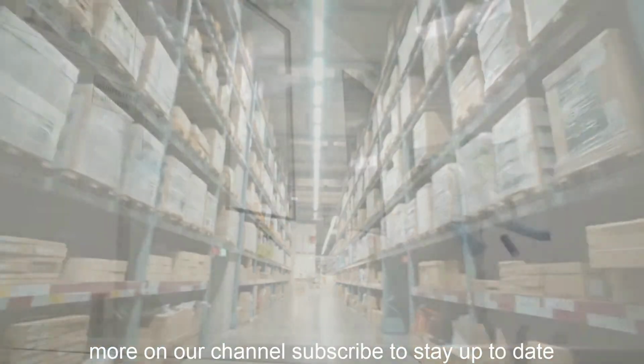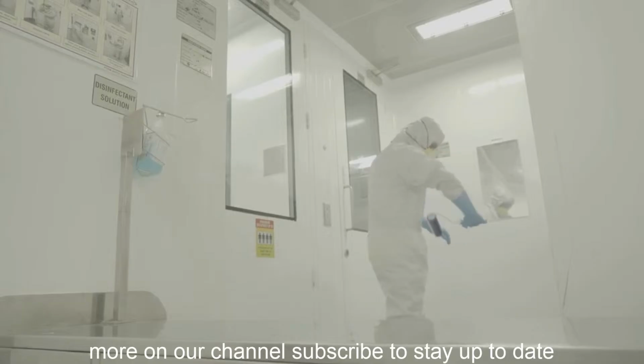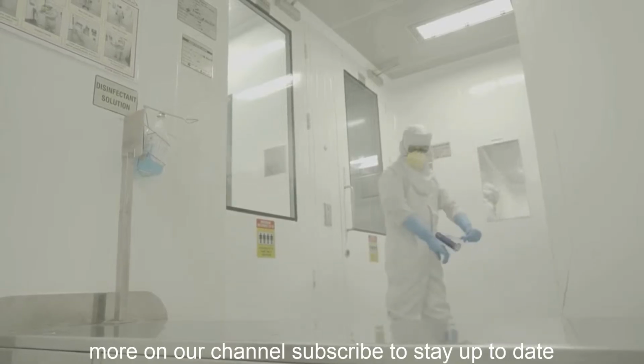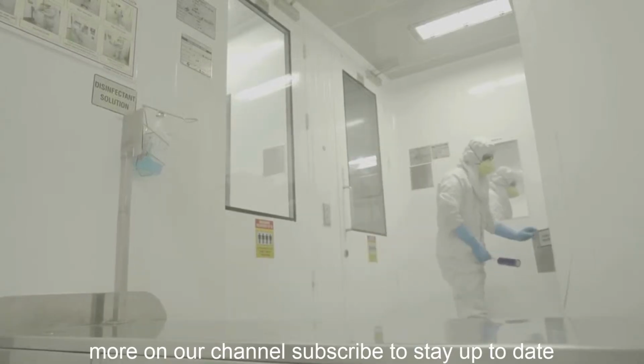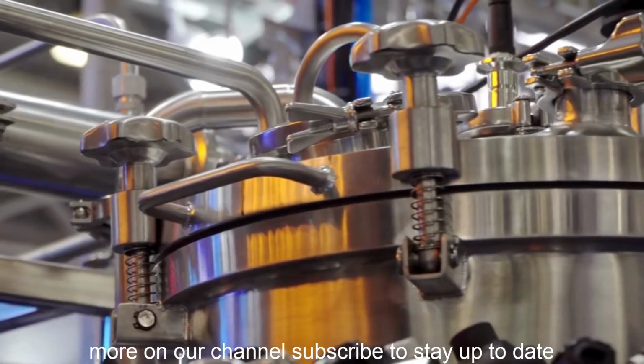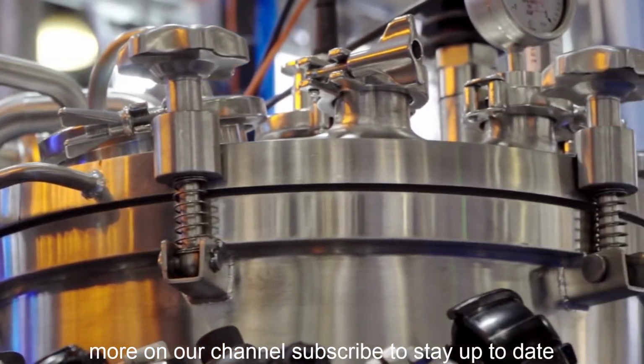These areas should be appropriately segregated, often with physical barriers, airlocks, and differential air pressures, especially when handling potent compounds or sterile products. Surfaces, walls, floors, and ceilings must be smooth, impervious, and easy to clean and sanitize effectively.